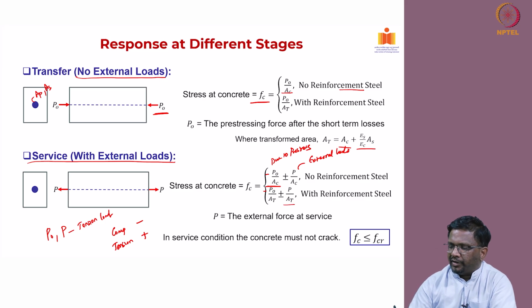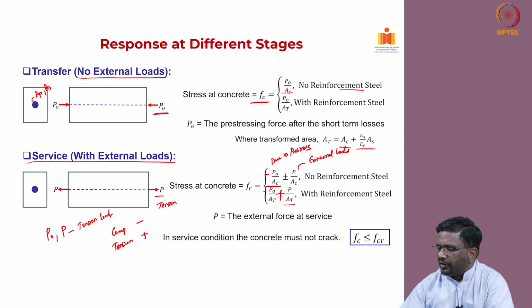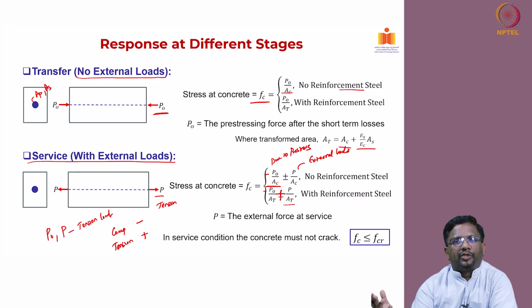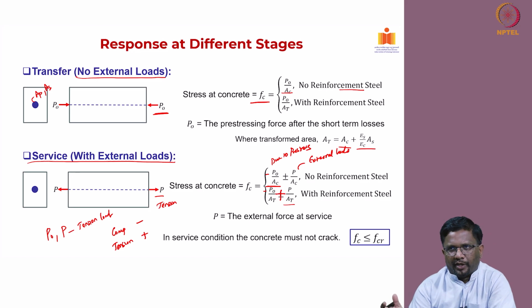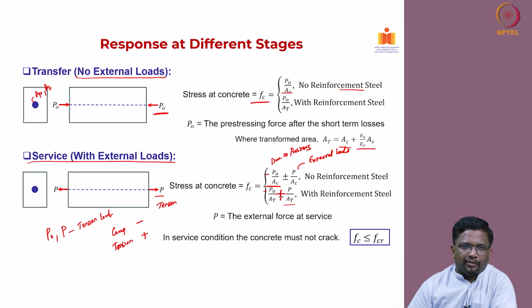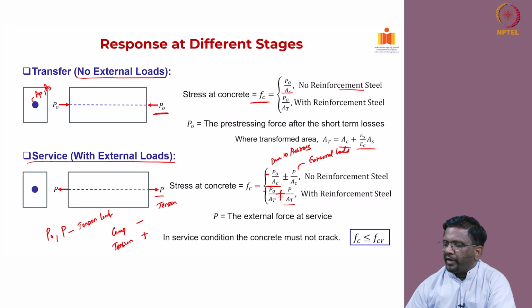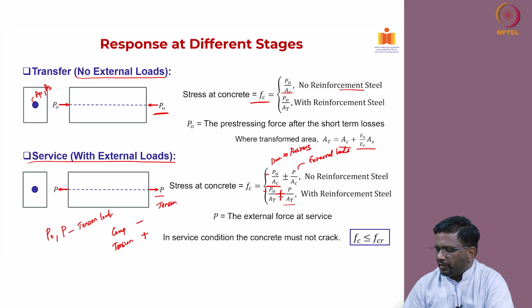So, now in this case it is in tension. So, the sign convention for this case will become plus, but you can also have axial compression. In that case the effect of P will be negative, right. So, the stress you have to put negative here. So, in this way we can calculate the stresses under service loads.